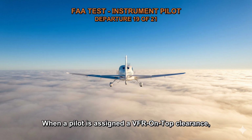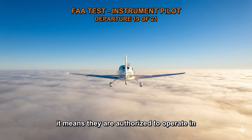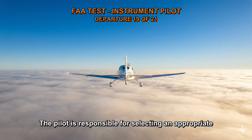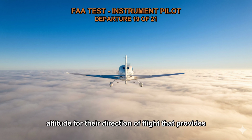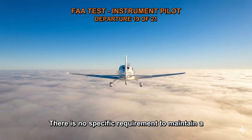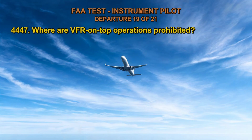When a pilot is assigned a VFR on top clearance, it means they are authorized to operate in VFR conditions above a specified minimum IFR altitude. The pilot is responsible for selecting an appropriate altitude for their direction of flight that provides adequate separation from other aircraft and terrain. There is no specific requirement to maintain a cardinal altitude plus 500 feet in this situation.